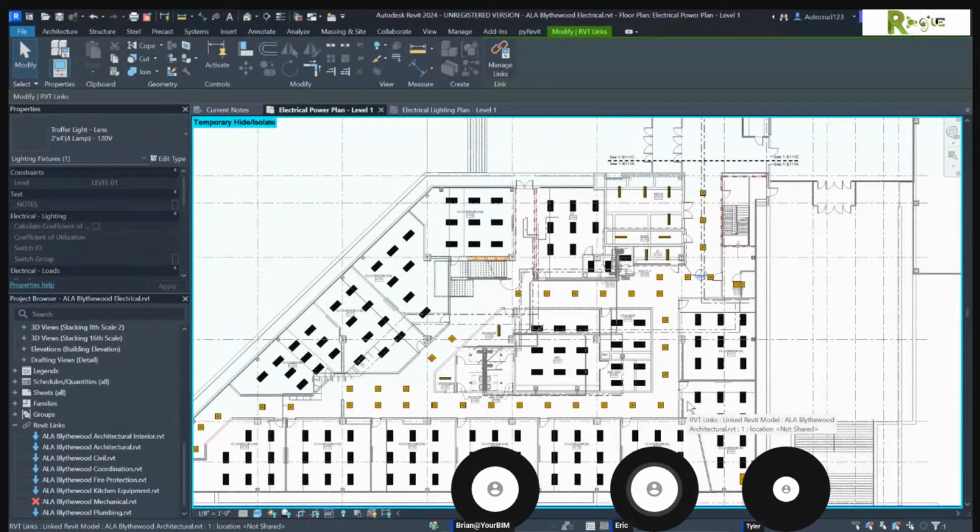I mean, you got to remember those lights are in a different file. So we're in the electrical. Those are in architectural. Yeah. I can't for the life of me think about how to turn that off. I know how to do it easily, but it's something we try and avoid doing. You would have to go into the link itself and set its visibility, but we want it to be set by the master view. Could we turn transparency off or on or?